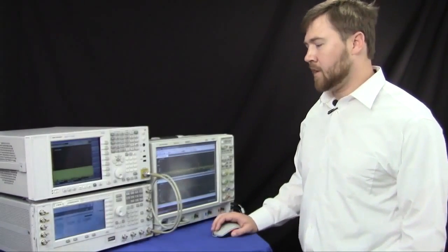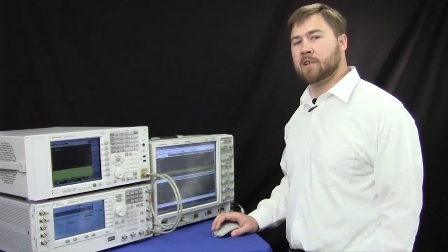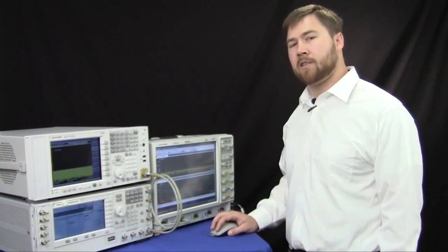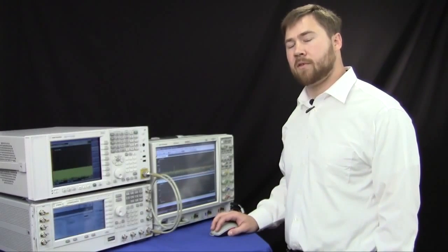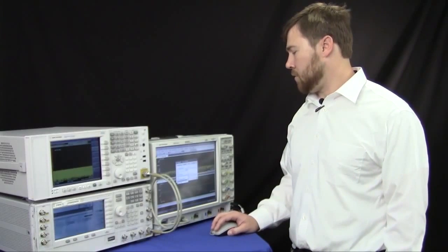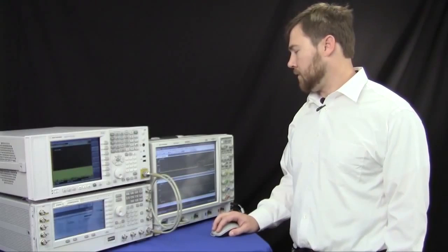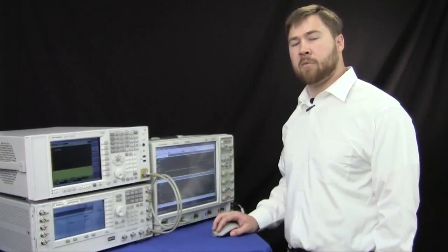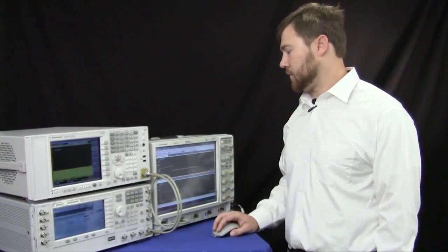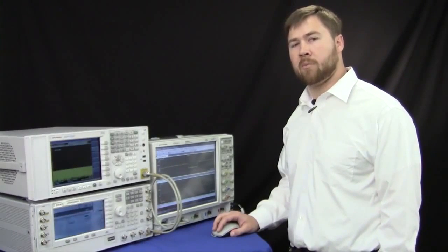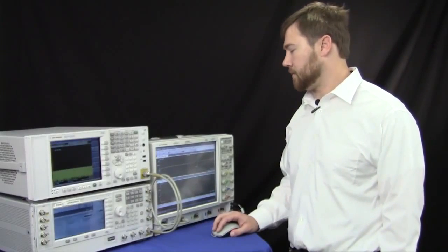Now I have my source sweeping at X band, 900 megahertz wide at a constant amplitude, in this case 0 dBm. So in order to correct the amplitude flatness of the IF, I'm going to go in here into measurement setup, average, and I'm going to turn on continuous peak hold. You can see now that the source is sweeping across, and it's giving me a frequency response of my IF. So I'm going to let this run through several times. You see my source is sweeping along in about 20 seconds across the 900 megahertz.